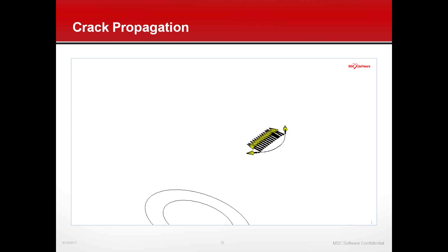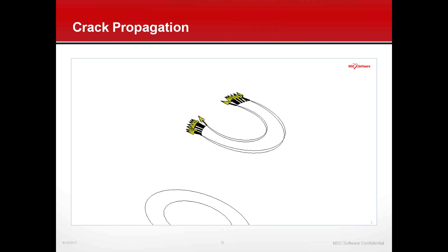And similarly, in this outline plot, you see it starts out as a single crack. It hits the inner part of the cylinder, which is then treated as a boundary, of course. It splits up the front into two fronts. It goes around, and it almost makes it at the end. I would have to have a much higher mesh density to be able to resolve what is happening at the end. It's a challenging situation to get it to grow all the way through.